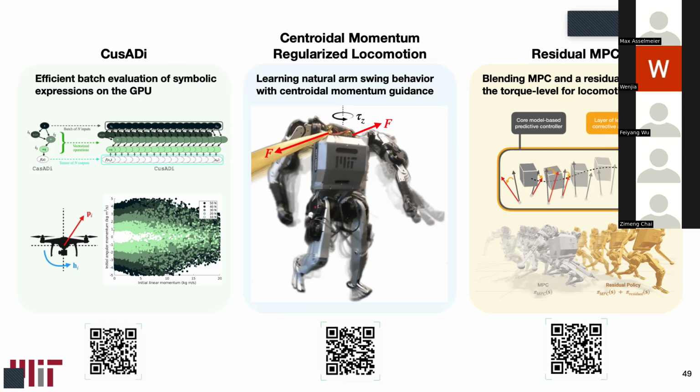Thanks. I can say a little bit on this question. We actually used a different centroidal momentum formulation and studied it in purely model-based work. We tried to do a feedback that regulates the centroidal momentum dynamics. It's like an ADMM type of program. I'm not sure if you've heard of it. Yes, distributed trajectory optimization. It was very hard to converge with the centroidal momentum, so we used something called the equal momentum ellipsoid to have different ways to parameterize the inertia tensor. But it's still hard. The numerical optimization doesn't really work very well.